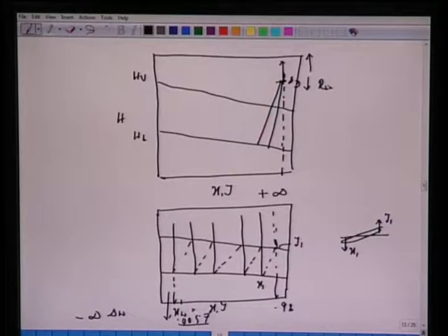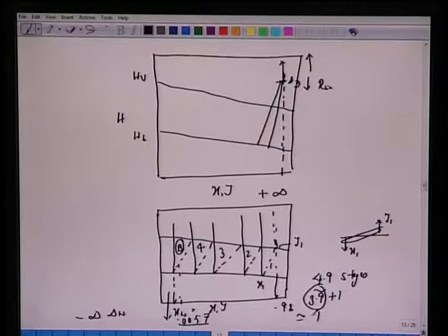Not necessarily would you be able to reach this point exactly, you have to do the calculation, at least you reach this. But notice that the last tie line which you draw will correspond to your boiler. So if you have done it graphically correctly, you should be able to show that you get 4.9 stages, which includes a boiler. So essentially we have 3.9 plus 1. So 1, 2, 3, 4, and we have this 4.9, which is just greater than this 0.0057. So essentially we have 3.9 stages, or 4 complete theoretical stages, plus 1 boiler.